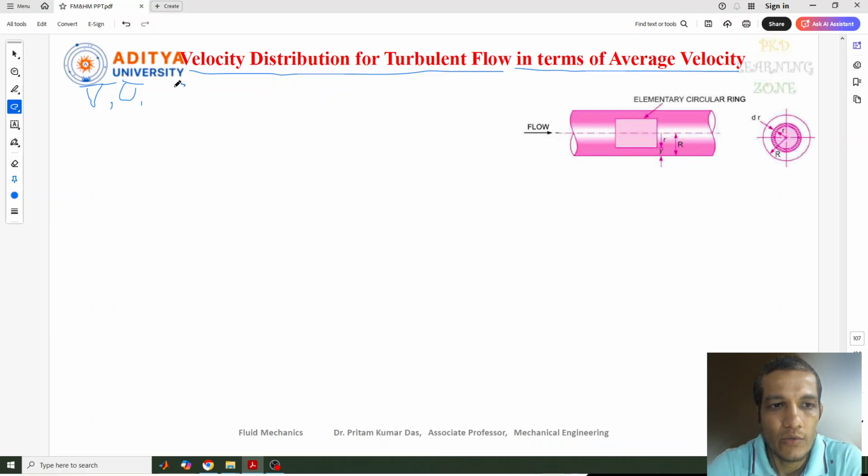The total discharge is Q, and the continuity equation is Q equal to AV, so we can write V equal to Q by A, where V is the average velocity. So V bar or U bar equals Q by area, the total discharge by area.